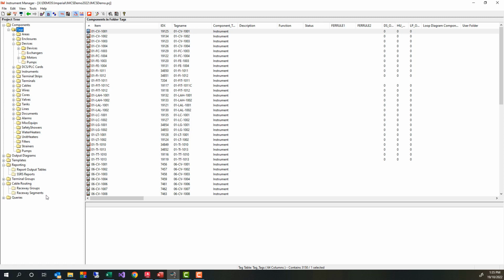Elementaries circuits are normally bespoke or hand-designed in CAD. As soon as a circuit becomes repetitive, it is worth considering developing it in Instrument Manager. Elementaries is a rich set of electrical tools and requires a separate demonstration of about an hour. Elementaries, while originally developed for panel layouts as the name implies, is now also used for cable modelling.